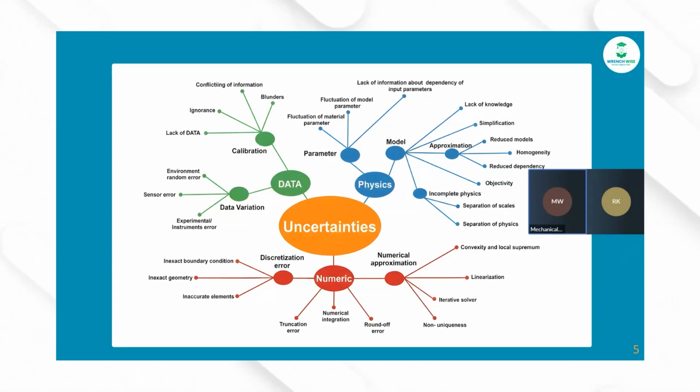There is also the concept of fluctuation of material parameters. I'm talking about, let's say, thermal conductivity. Thermal conductivity varies with temperature when temperature goes beyond a certain threshold. If your simulation doesn't take into account how thermal conductivity varies with temperature, you will see the wrong results. So it's a lot of back and forth between the safety engineer and the solver to fully describe what your actual physics is, and then try and approximate how you can solve it in the CFD solver package.